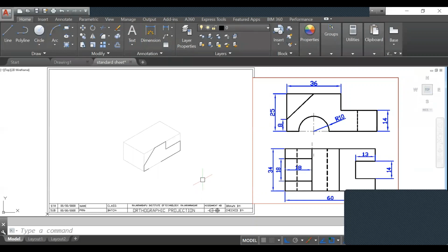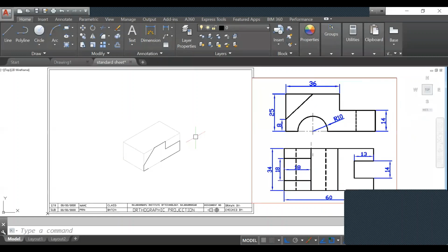After that, what we have to do? Next part, yeah, we have to give this particular thickness to this one. Thickness, because this is the front portion. Okay, so we have to give slowly thickness to this one, and the thickness is total width 34. Because if you observe, you have to look into both the views. This circle is throughout, you can see it is not visible in the top view, so there is one hole throughout with a radius of 10 mm.